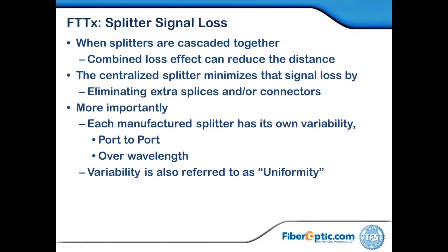Now, when you calculate budget losses through a splitter, it's some pretty basic stuff. You may have had some of this in basic electronics, but we're going to have pretty high losses in this physical plant. Unlike what we normally think of on a pole for normal telephony, our losses are going to be pretty substantial. And it comes from the fact that the splitters are passive and they split the signal. This is not unlike a typical cable TV coaxial or RF splitter. In fact, all of the light still goes around the 3 dB rule of power, which means every change of 3 dB you double or halve.